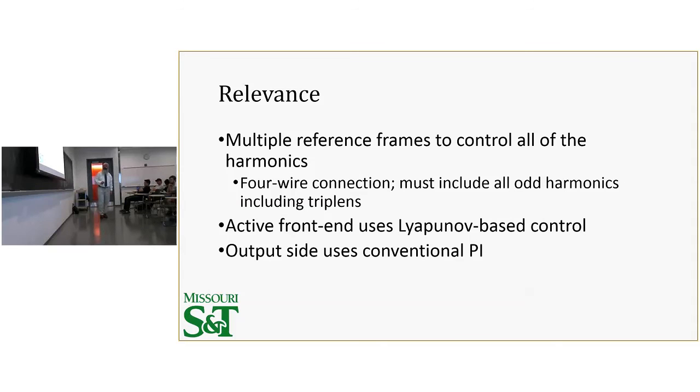Again, the relevance is the multiple reference frames to control all the harmonic content. The active front end uses that Lyapunov-based control that I mentioned earlier, but the output side is just a conventional PI in that harmonic sequence.